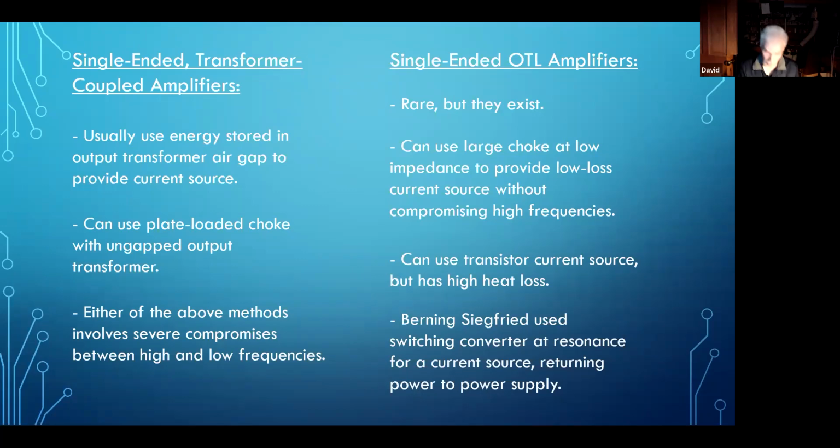They're using a transistor current source, but they're modulating the current source in such a way as to increase that current when you need it most and decrease it when you need it less. That basically allows you, at least theoretically or ideally, to get double the power that you'd get out of a dumb current source that's just operating at a steady-state current.